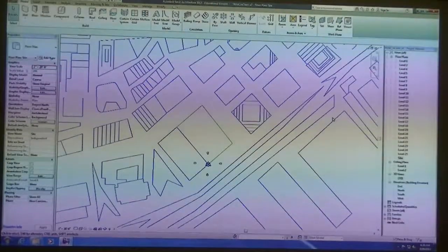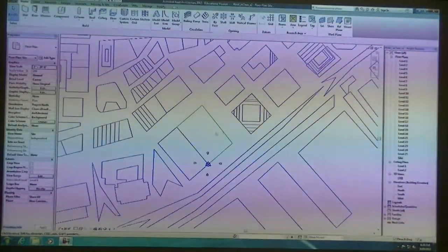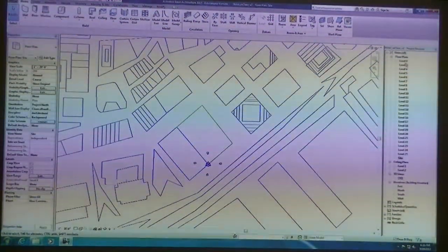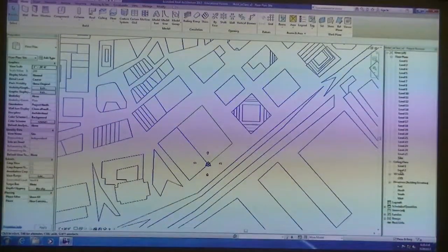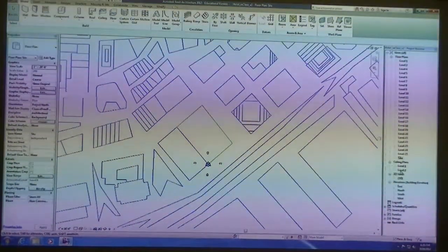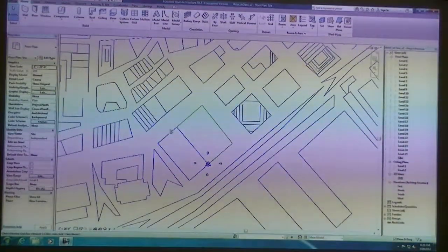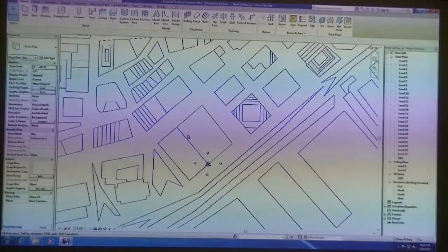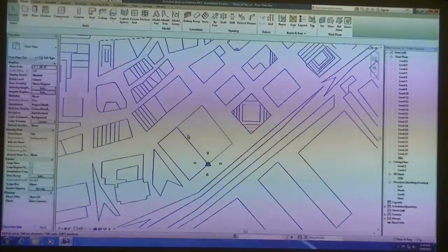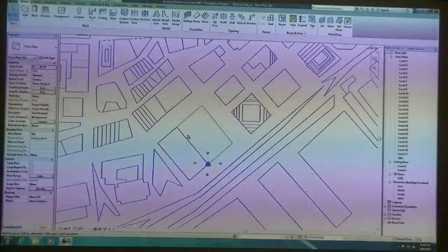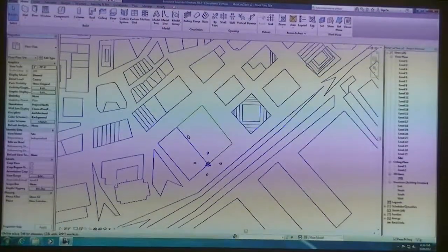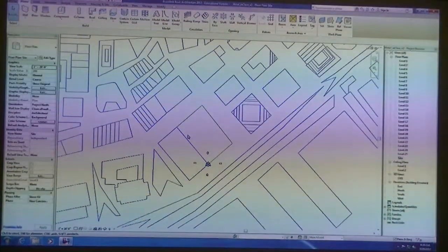And while we're working in Revit, everything that we do essentially eventually has to end up on a drawing sheet somewhere. And when we apply or drag any kind of floor plan onto a drawing sheet, it can only rotate 90 degrees. So we can't actually model in this particular direction. We actually need to rotate our view and then also orient true north back to its original, or relative to the way that we rotate the site.